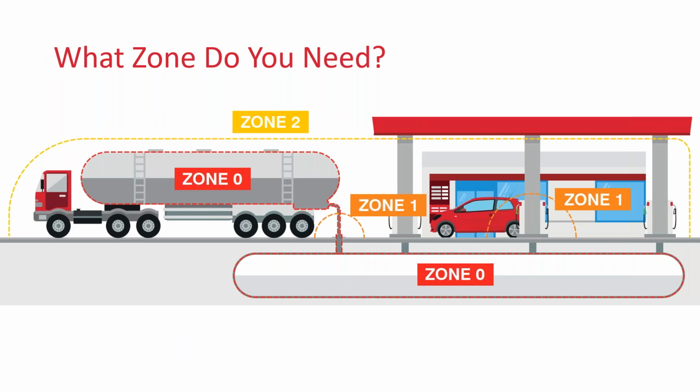Knowing which zone you need can be a challenge, and this is because every application is different, as I mentioned earlier. The site needs to be independently classified to determine things such as the types of gas and dust present and in what volume, plus also the level of ventilation on site. Ultimately, it is always recommended that hazardous area classification is done on site by qualified personnel, applying the relevant standard, 60079-10.